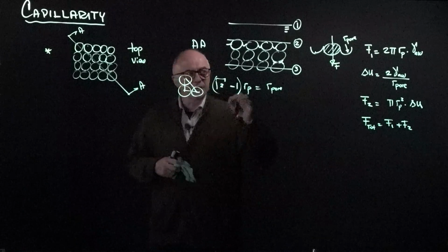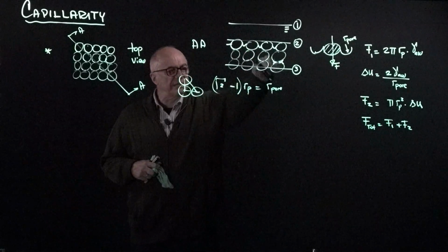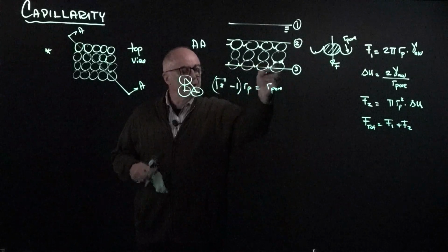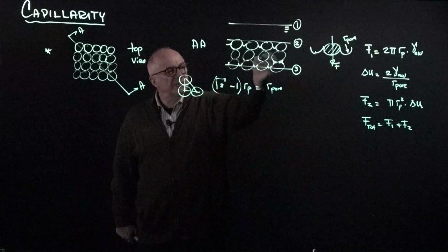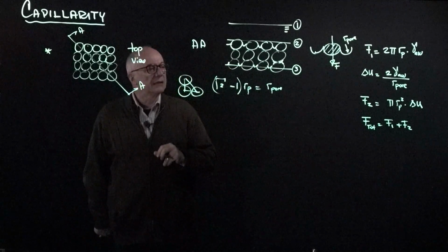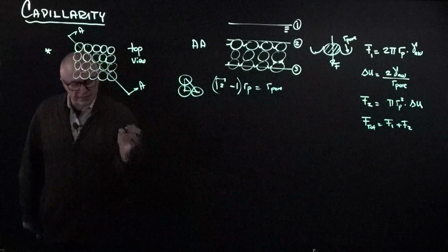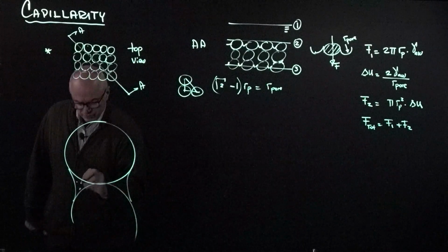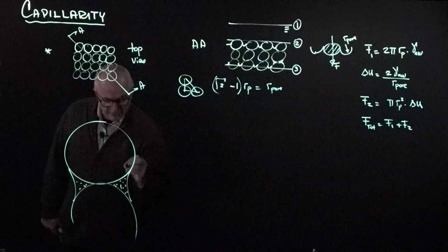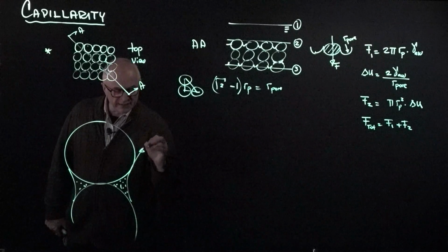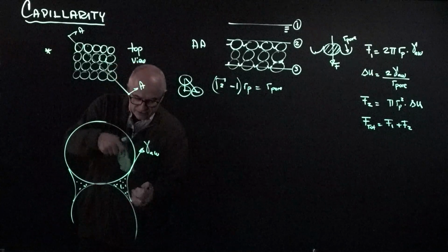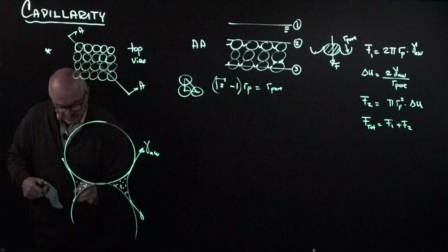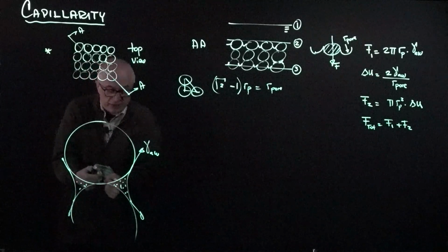Finally, let's consider the case when the water has evaporated enough that it has reached this level. So when the water table is at position 3, the menisci may be here. And when it is there, the water may have remained at the menisci. That's called the pendular regime. And when it is in the pendular regime, now the story gets more interesting, because if these are the particles and you see the menisci, and this is the water here, we have 2 effects. On the one hand, this is the interfacial tension air-water pulling, and so if you imagine that both sides are pulling and also pulling from the other side, this is going to put the meniscus in tension. They are trying to stretch the meniscus out.